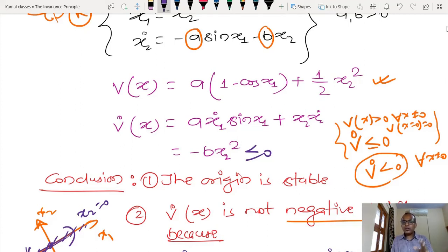So if you understood the idea, now we are just going to derive some extra condition, how to generate this set. That is just the other extension. Okay, so the idea is pretty simple. You can take any Lyapunov function, and suppose the derivative of the Lyapunov function is negative semi-definite. Now you can add extra analysis such that you are able to show that V dot x equals 0 only at the required point, meaning the equilibrium point. If you are able to do so, then I can talk about asymptotic stability. In some cases, I can also talk about global asymptotic stability if V(x) is radially unbounded. So just by seeing the rate of change of the Lyapunov function, if that is negative semi-definite, then I can talk about asymptotic stability. That is the basic idea of LaSalle's invariance principle.